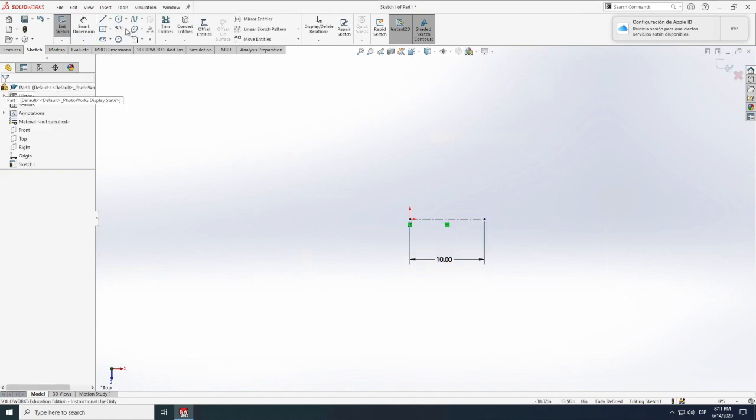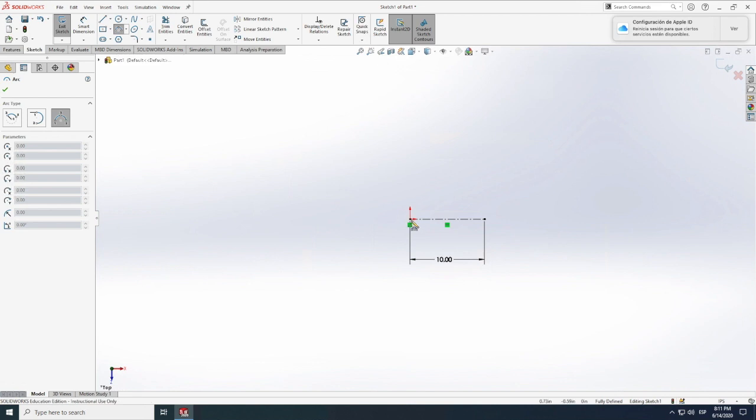And now, well, there's different sort of arches you can do. I usually use these two, so those are the two that I'll just go ahead and explain. 3-point arch, fairly simple thing in here. You just go 1 point, and then you just drag and make a circle as big as you want. And you see that small arrow, which I'm trying to point at, but it's moving. That would be the center of that circle that you're drawing.